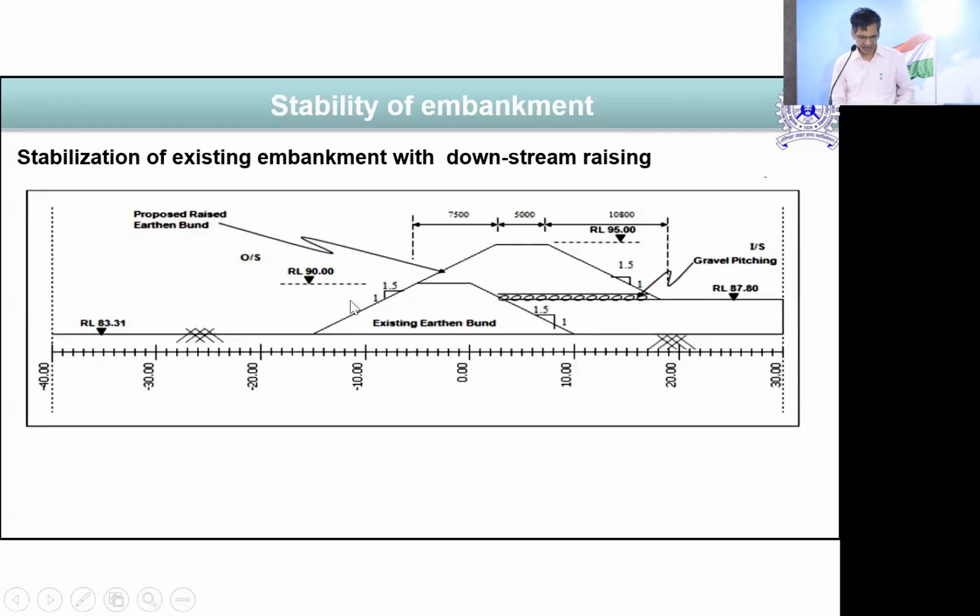So here, suppose it is not written as the earthen one, it will be fly ash. So here suppose I am using fly ash. In this case, if you see, they also have 1.5:1. I mean the slope is very steep compared to what they see in a tailing dam, 2.5 or 3. But these are all there because initially these fly ash dikes were simply designed as small embankments or dikes, because dams and dikes, so dikes obviously lost their importance as a water retaining structure.